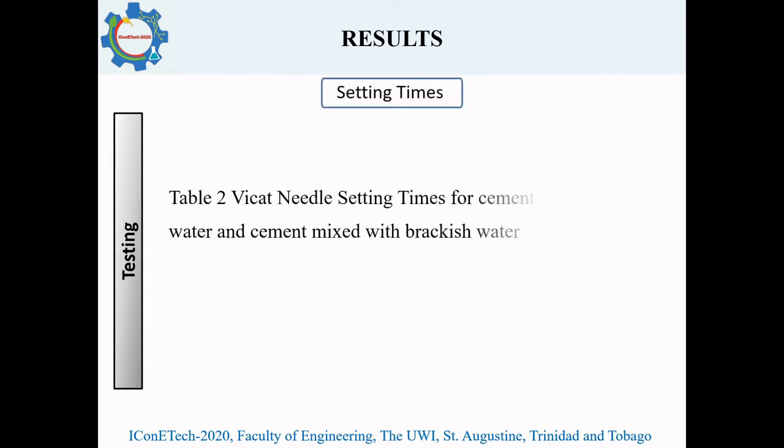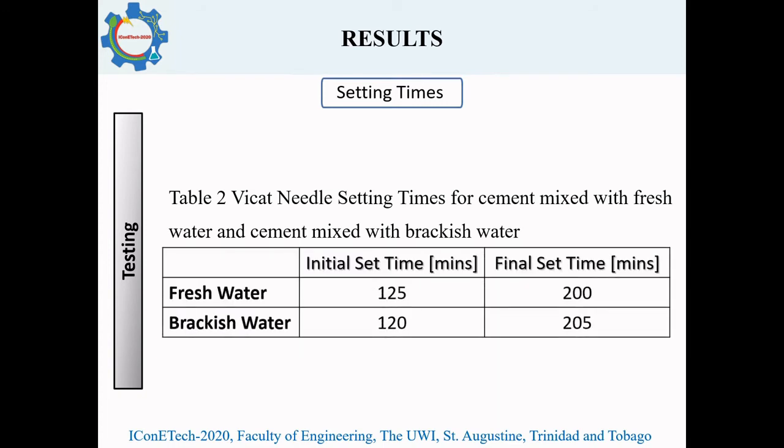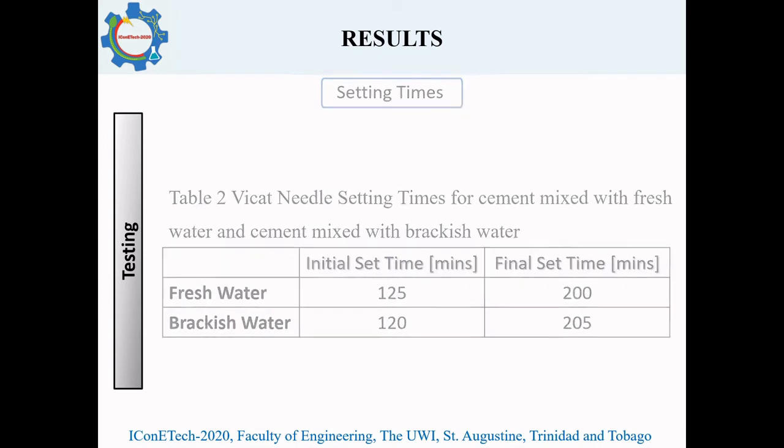The initial setting time of the brackish water was only 4% shorter than for the fresh water, a difference of only 5 minutes, and the variation in final setting time for brackish water was only 2% greater. Thus, there was no significant acceleration or retardation of the setting process by using brackish water.